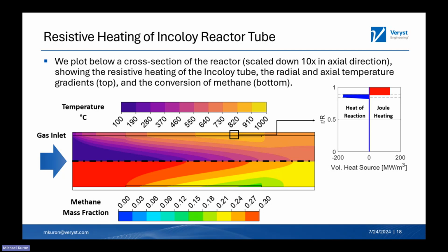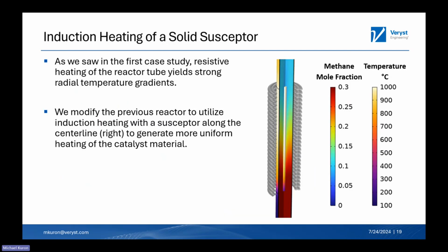And so one of the downsides of this type of electromagnetic heating, similar to the gas-fired heating with a conventional system, is that all of the heat is applied from the outside in, and we develop strong temperature gradients and have to therefore create temperatures much hotter than we otherwise need to drive the steam methane reforming reactions.